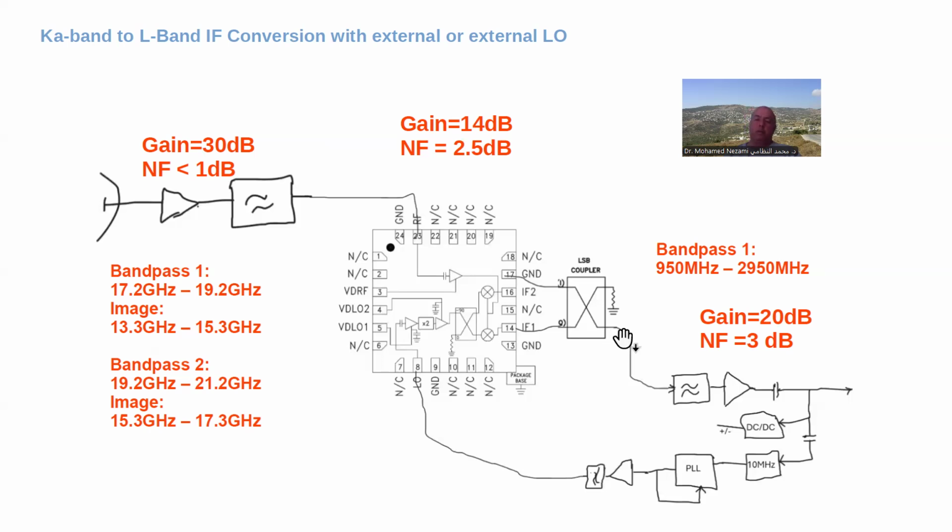to actually cancel out one of the sidebands and get a single band signal in here, which is the IF in this range. And then I'm going to use an IF section to amplify it. Of course, the images are in this image here and this image in here for both the bands. I need to build a bandpass filter, this bandpass filter in here. Now, realize this is really an image rejection mixer, this technique in here. It's single sideband, but still I would still need to reject the image in here.